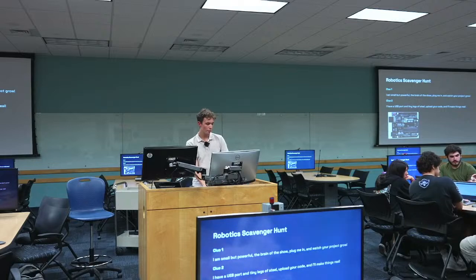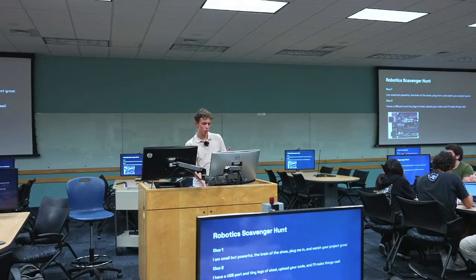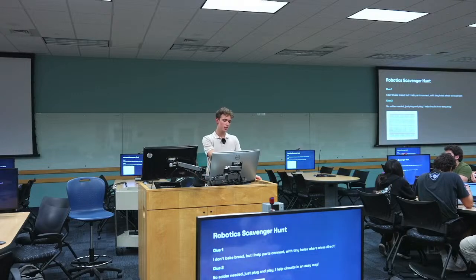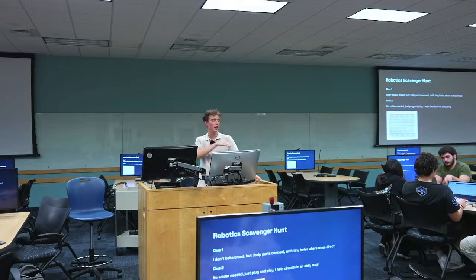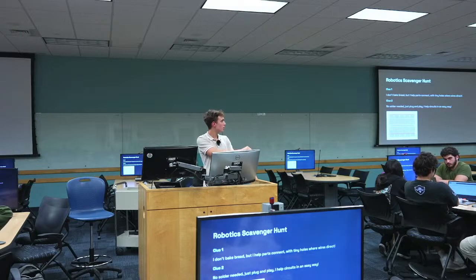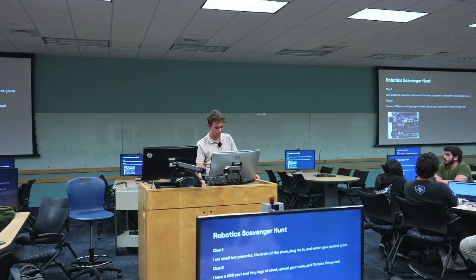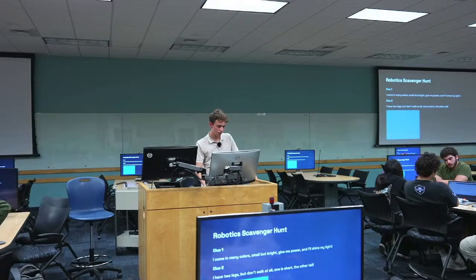so the structure, how everything works, how the energy flows. And actually, one very important thing about the breadboard that I want to mention, the previous one, is that if you see the structure of it, you have positive and negative poles. And you can see that there is a separation line in the middle. You guys found it, the breadboard? We're coming back to the previous one, but I wanted to point this out. If you see how the energy flows, it's not like a row. You can see there is letter A, B, C, D. If you connect one wire to A, it's not that it's going to connect the A row. It's going to connect the vertical line, the column. That's very important to note, because if not, we're going to run into some issues in the future. But that's it.